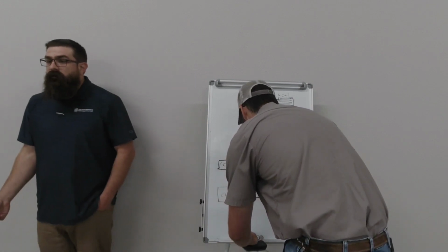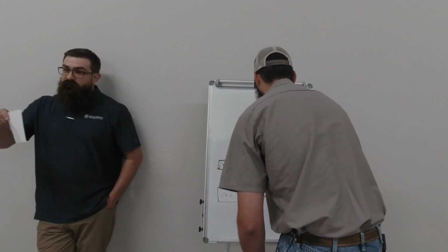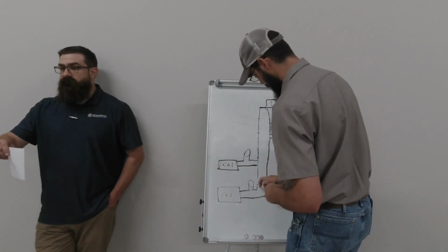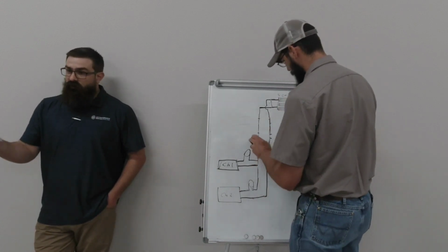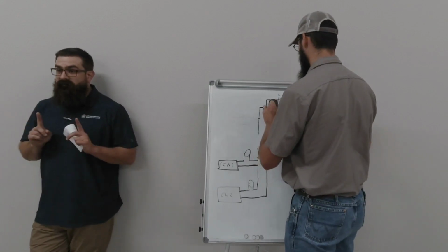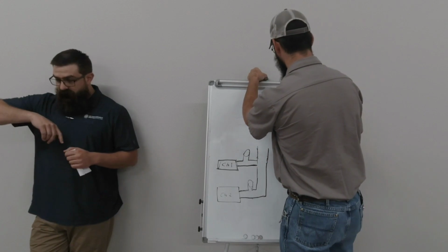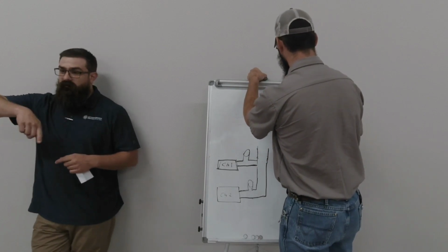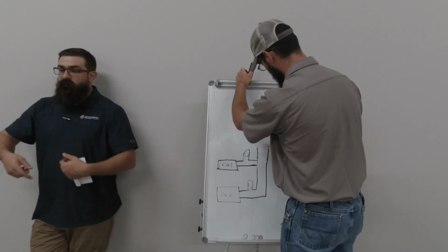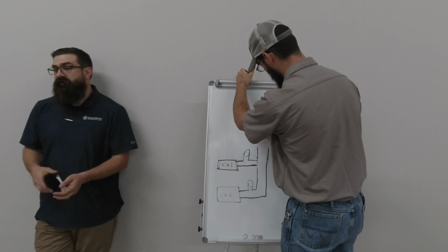515 Congress is a building downtown. So it uses city chilled water, right? Which is really cold, like right above freezing. It's got glycol in it. You pass that through a heat exchanger, and then there's only a set of pumps in the building that does the building's chill water. So they circulate the building's water over a heat exchanger that's got water coming from the city to cool the loop for the building. So they don't have a chiller. They just have these two heat exchangers.